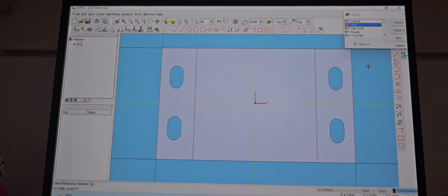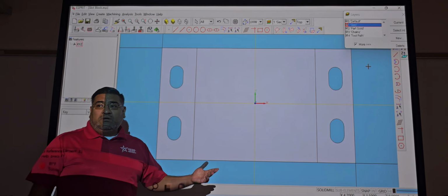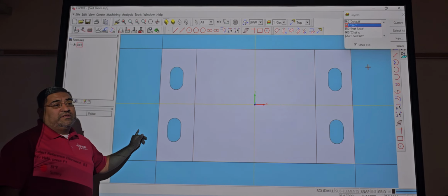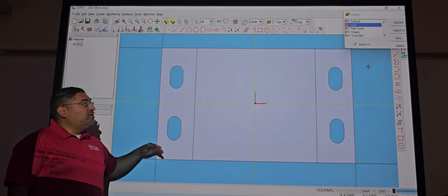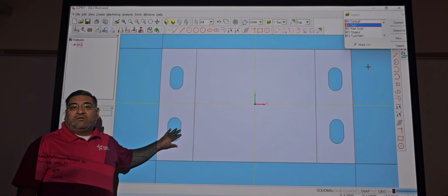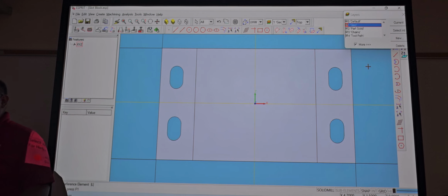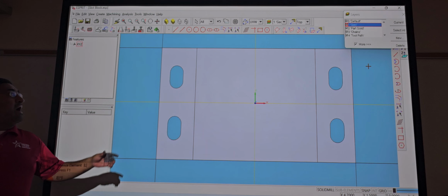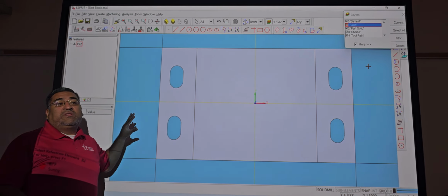Guys, I'm just doing this in this order right now because I'm showing you you gotta do the facing. But if I was doing this in real life, I would take this one at least 250 thousandths over here and 250 thousandths down, right? Because I know that's gonna help me out whenever I'm doing these 2 steps on the sides. But I'm teaching you one operation at a time, okay? So that's why I'm doing it this way. But normally, to save time, to make it faster, I would already make my square bigger than this, because I could use those lines with that chain again.